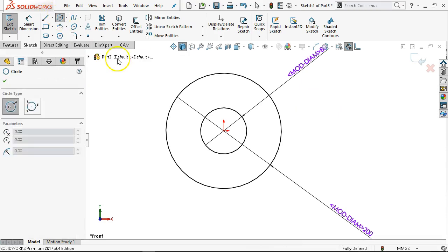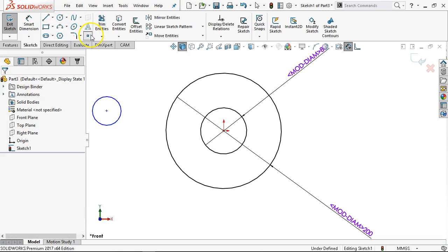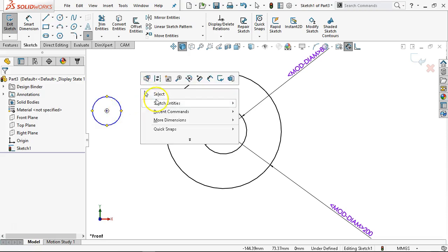okay, so going back into the circle, whenever you drag over an existing circle, you're going to have the 4 diamonds, one at each of the quadrants. And then you're also going to get the center point of the circle. So even if I come out here, draw a circle, and let's just go into the point. I drag over top of it, there's the center point. I go to a quadrant, I'm going to be able to pick that coincident, vertical, horizontal, whatever was part of